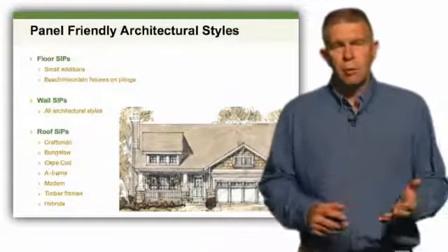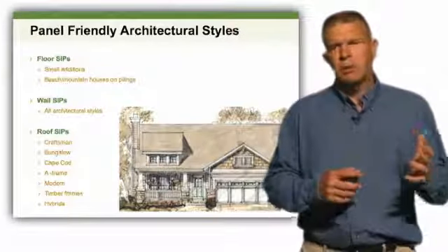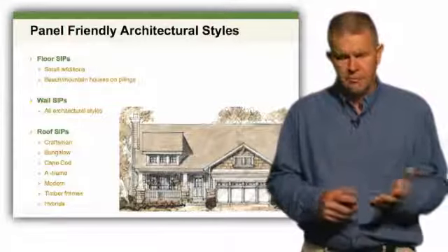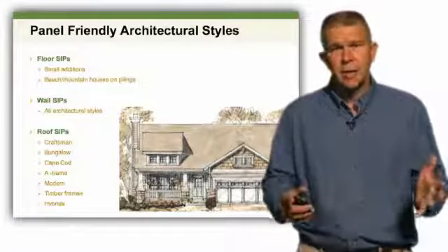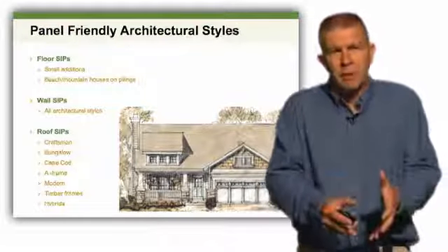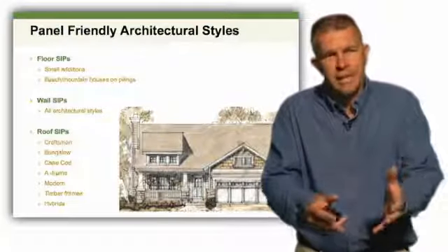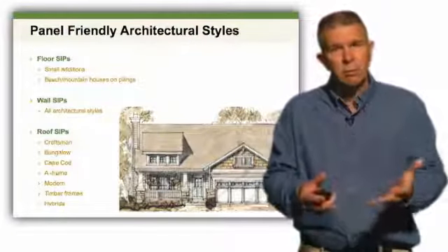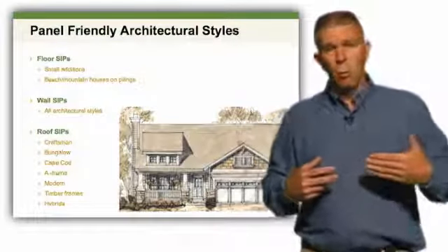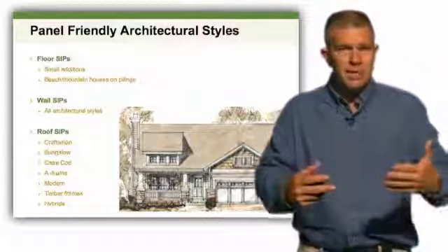The roof SIPs, of course, are a different issue. A lot of misperception follows whether or not roof panels should or should not be used. In some cases, the answer is no. Let's not force SIPs into the design. Trusses work incredibly well. That's the way the building was designed. That's the way the foundation was designed, to be built with trusses. We've got flat ceilings, and it works perfectly well. If we're only going to use wall SIPs in that scenario or that design, so be it.